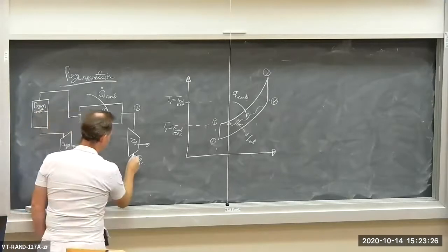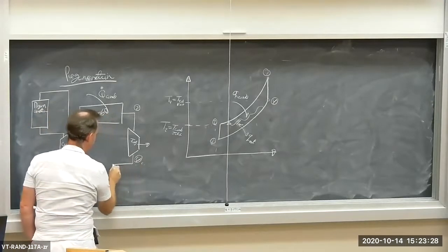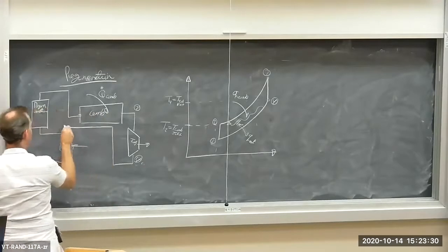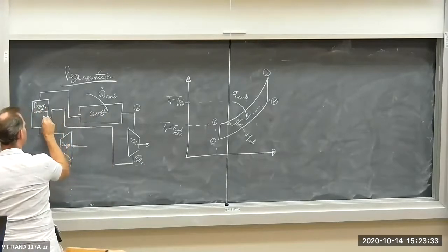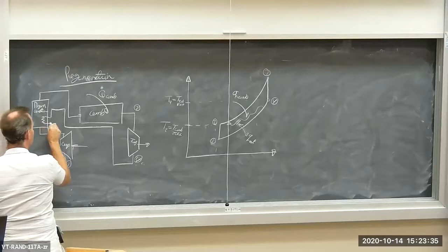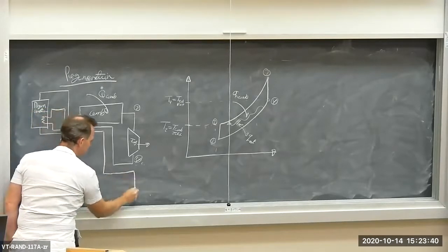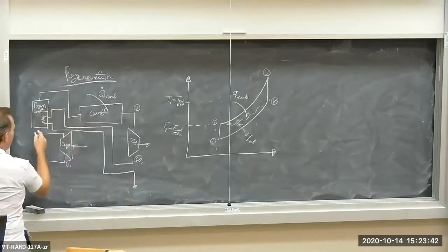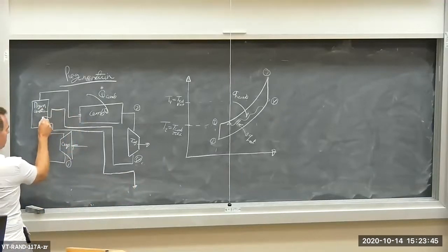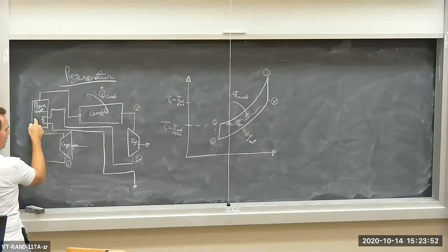And I can take the exit turbine flow, which is hot. I could put them in thermal contact, so this will be a channel or a duct containing the very hot turbine exhaust, and this channel contains the relatively cool combustor inlet gases.